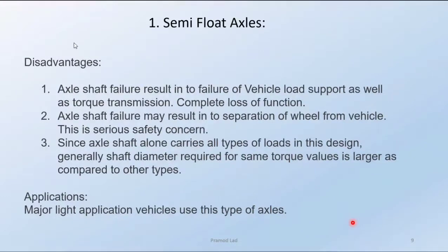So what are the disadvantages of semi-float axles? First, axle shaft failure results in failure of vehicle load support as well as torque transmission. So complete loss of function.